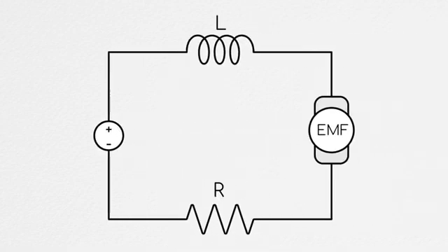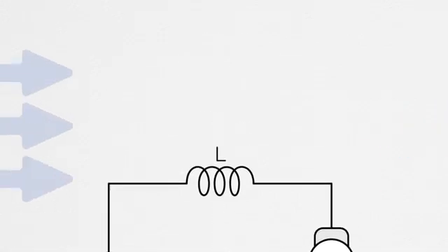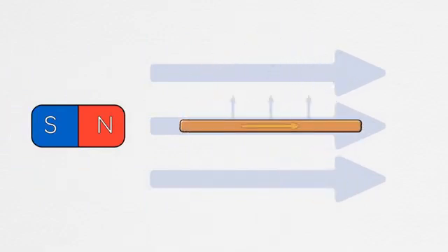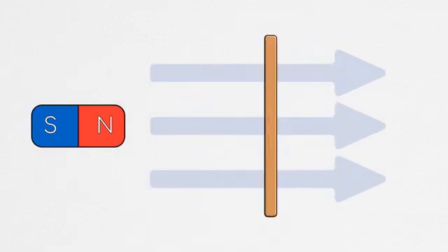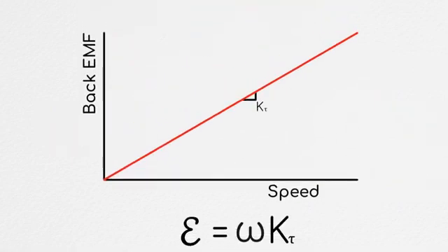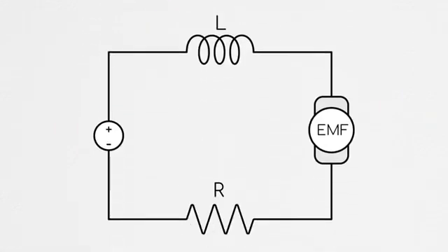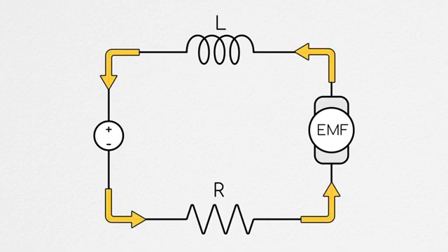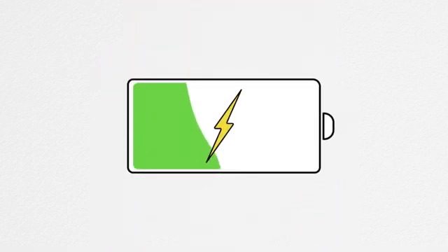In such situations, the key to converting mechanical power into the electrical domain is the back EMF generated by spinning the motor. As we've discussed a couple of times in this series, the back EMF is a voltage potential generated due to the motor coils rotating in its magnetic field, and it is approximately equal to the motor's torque constant multiplied by its angular velocity, assuming you have your units in check. If this back EMF is greater than the voltage supplied to the motor, then the net voltage on the system will drive current up from ground back into the supply. If your motor is connected to a battery, this would begin to recharge your battery. So that's the general idea.